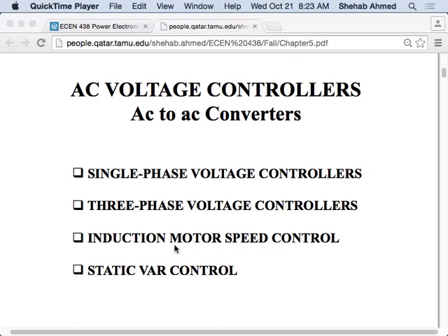It will develop this back EMF voltage when the motor rotates. Initially, the motor does not have the back EMF to stop the inrush of current, right? But when the machine rotates, it will develop this back EMF, simply speaking. So as soon as you put the three-phase supply voltage across an induction motor, you will have a huge amount of current initially, and then the current will go to steady state, to be proportional to the output torque, for example. Okay, so that's how an induction motor works.